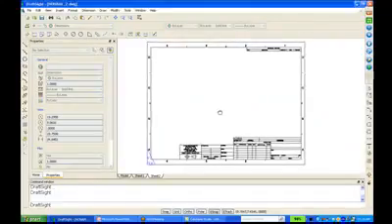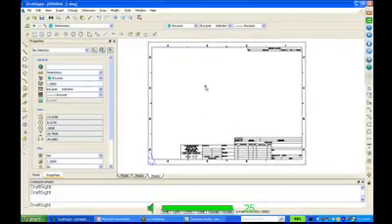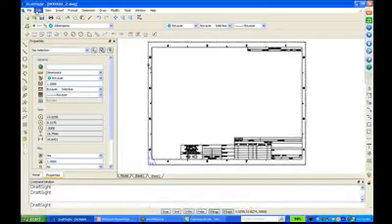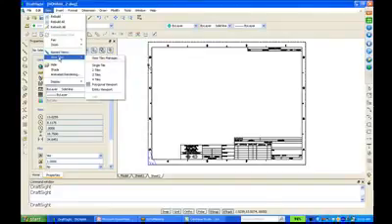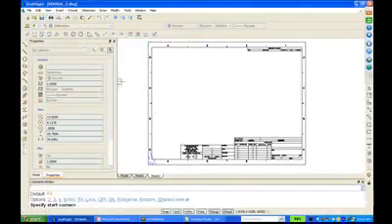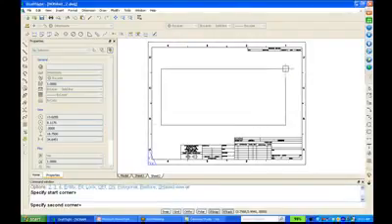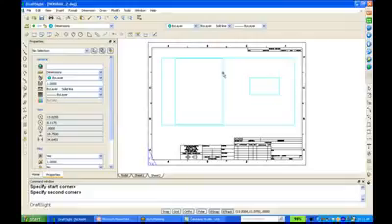But as you can see, I don't see any geometry. Well, that's because I don't have a viewport. I need to put one in. So if I go to View Tiles, and say Single Tile, it's just going to ask me for a rectangle. So I can say, here's a corner and here's a corner. And there's my viewport. I just put it in.